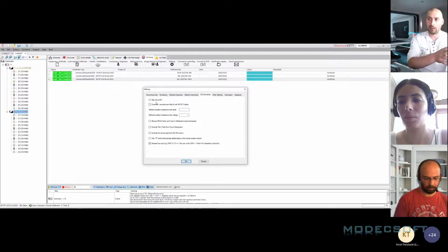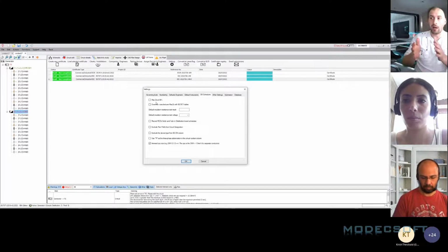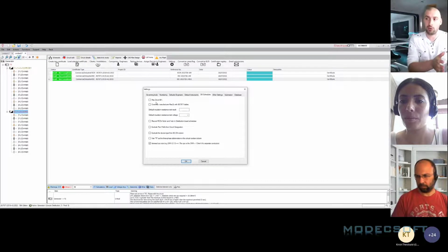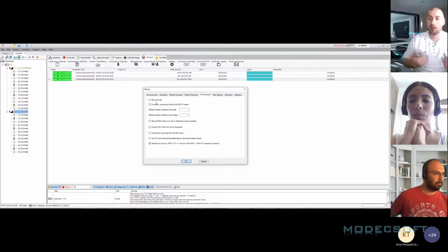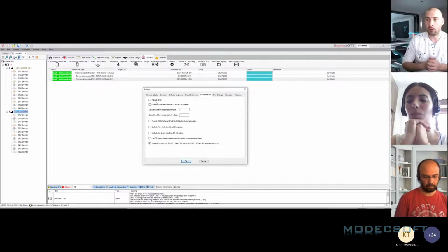That option's there because it was within BS 7671 for the regulations in an informative annex. However, that's no longer there, and there's no other options within BS 7671 to be changing your earth fault loop impedance maximum values or protected device values for any other reason. So we don't currently have that in there. If it's something that people require and need, it's something we can look at providing. But at the moment, you're the first person that's ever asked us, to be honest, if that's a possibility. All right, thanks. Got it.